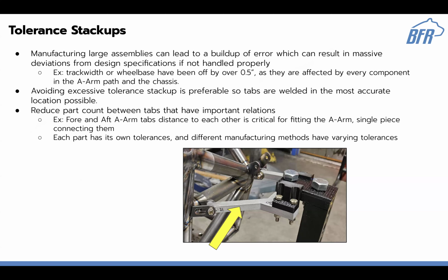And if each of these parts is having like 10 thousandths of an inch that are off, this starts to stack up until you might see, like in previous years, like we once had, our wheelbase was off by over half of an inch, which is a pretty significant one. Welding tolerances can be pretty bad sometimes, where you actually notice that it's off.